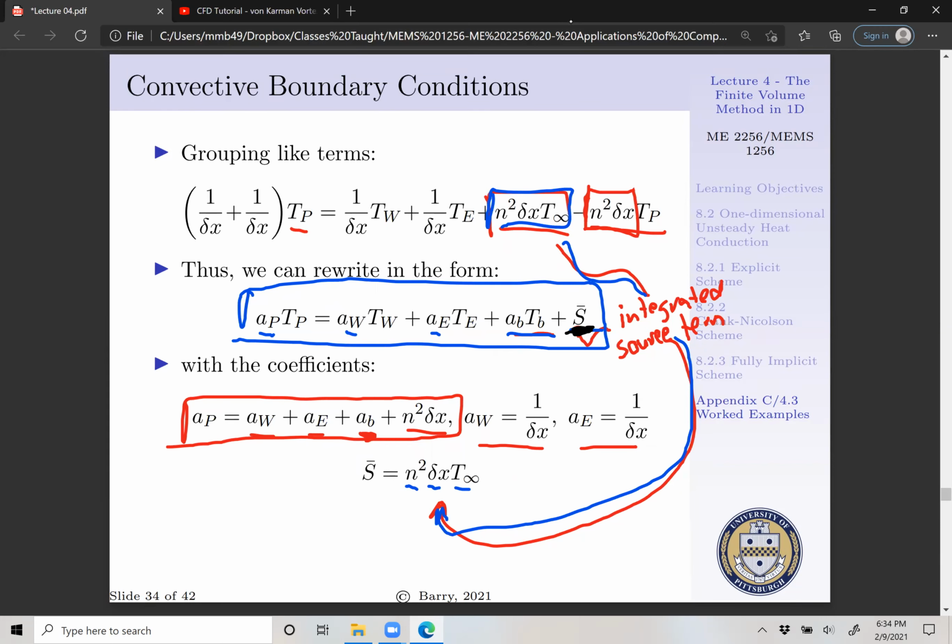We just tack on a constant value. This, of course, isn't talking about nonlinear source terms, which we'd have to spend a little time later on with. But as it stands, we could even tack on this source term formulation to our transient problem. Super easy. Just add S onto the end, and we're done. So that concludes, I think, almost everything we need to cover for one-dimensional diffusion.